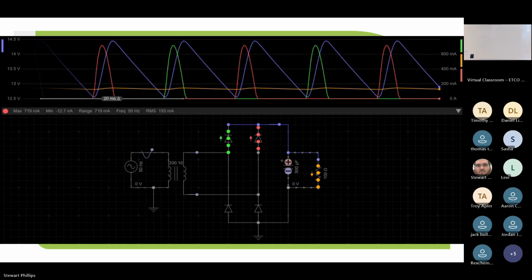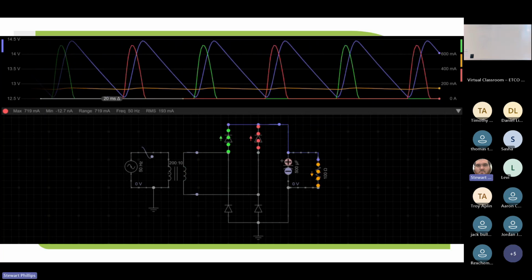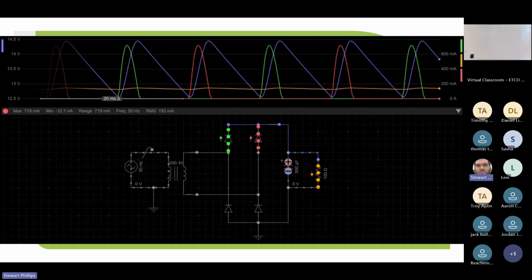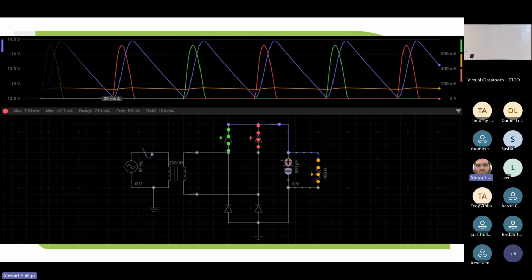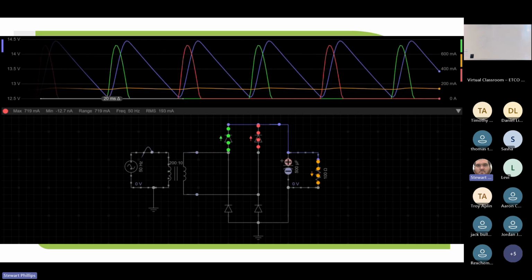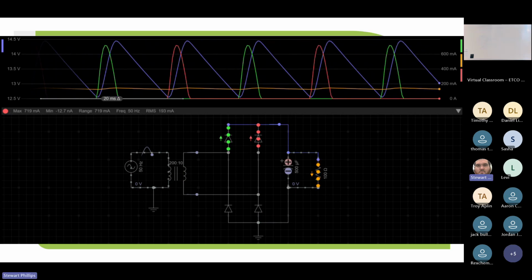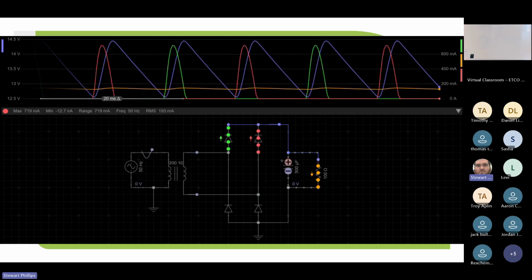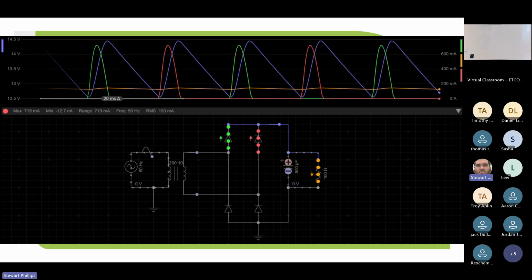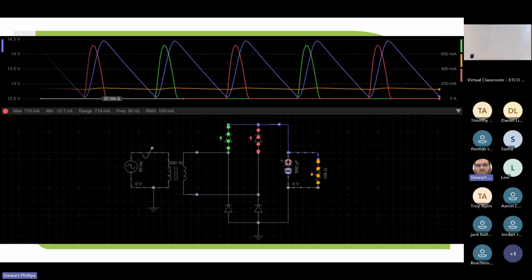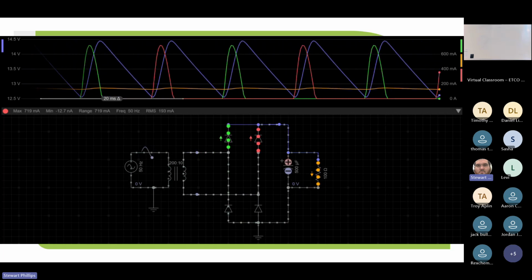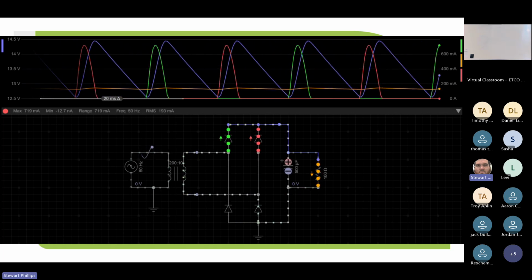smoothing. Sorry about the video, but as you can see, the orange line, which is the current actually flowing through our resistor or our load, is steady DC because we've used a capacitor as a literal charge and discharge bank.